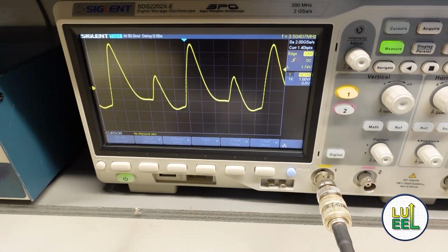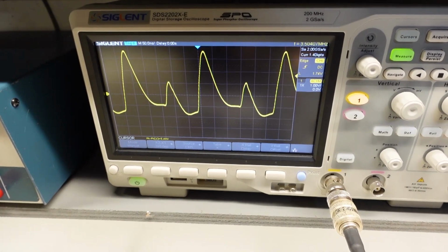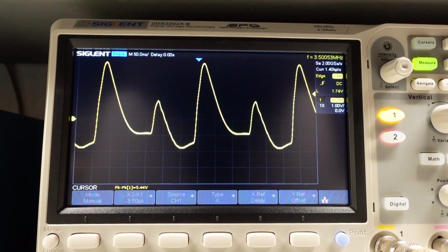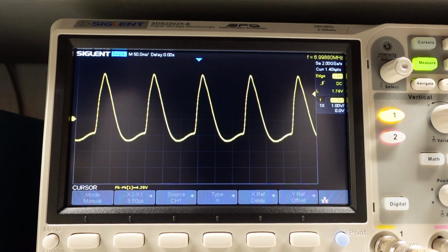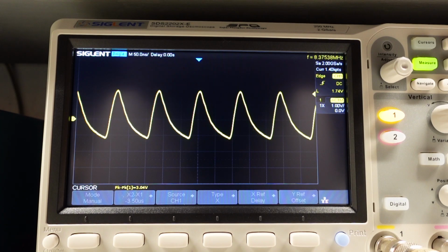In my recent Heathkit HG10 VFO episode, I examined its funky output waveform using my oscilloscope. By design, the waveform is not a pure sine wave. Instead, it's rich in harmonic content. It contains integer multiples of its fundamental frequency, which are then selected by rigs like the DX60 for driving an RF transmission on a specific amateur HF band.